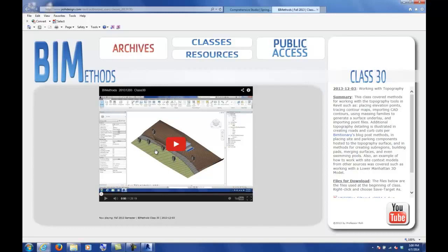You're really going to notice that when you take your rendering shot. If you're doing a camera view and you're standing in the street looking at the front of your building and you see your curb cut, that's probably where you want that level of detail, since you'll be that close to that location. I wouldn't do the curb cut on the back side of the building if you're never going to take a 3D view of it, because that would just be wasting time. So once you set up your camera views for your renderings, figure out where you need to go into much more detail.